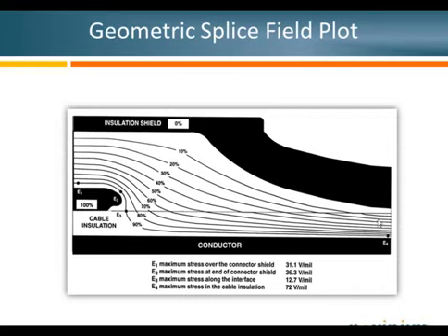And the difference is that with a joint, you're taking those equal potential lines that are running through the cable insulation, you're bending them and forcing them into the joint insulation and then back into the cable on the other side. Whereas if you looked at the termination, these equal potential lines come out of the termination into the air, so air is part of your insulation with terminations.